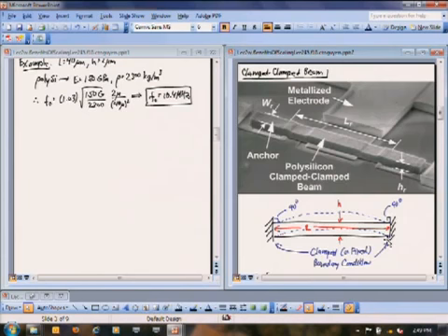But if you look at this beam, and this is the consequence of how we make this using that technology we briefly described last time, which we'll go into great detail later on, you'll see one consequence. You don't have a nice straight beam here. You actually have a beam that comes up over its anchor condition. The anchor condition is not exactly this; it can't hold it exactly to 90 degrees. Second, you can see that this beam has some ups and downs there, and these ups and downs shadow the electrodes.